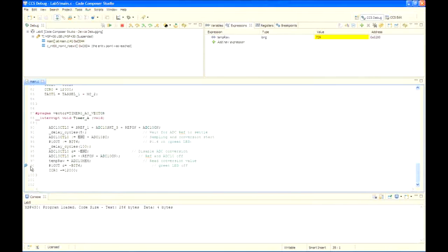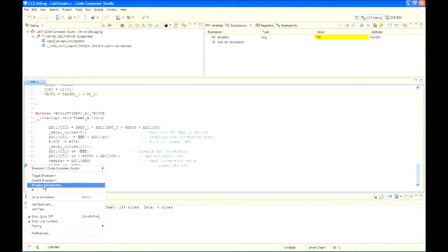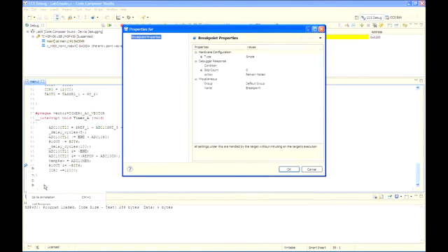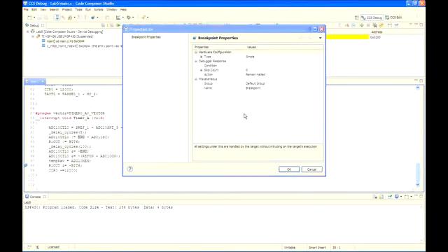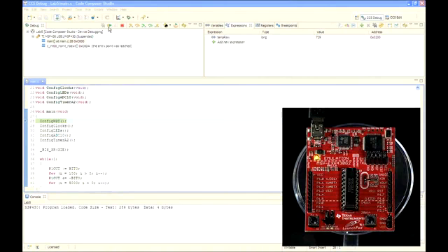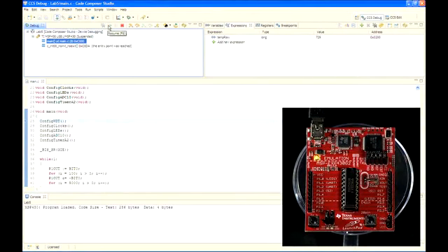Right-click on the breakpoint symbol and select Breakpoint Properties. There we go. Again, we're still having some difficulties with our capture system, so make sure you change the breakpoint property action from stop to refresh all windows as shown in step 18. Go ahead, say OK. Go ahead and run the code. The debug window should quickly stop at the breakpoint and the temp raw value will be updated.